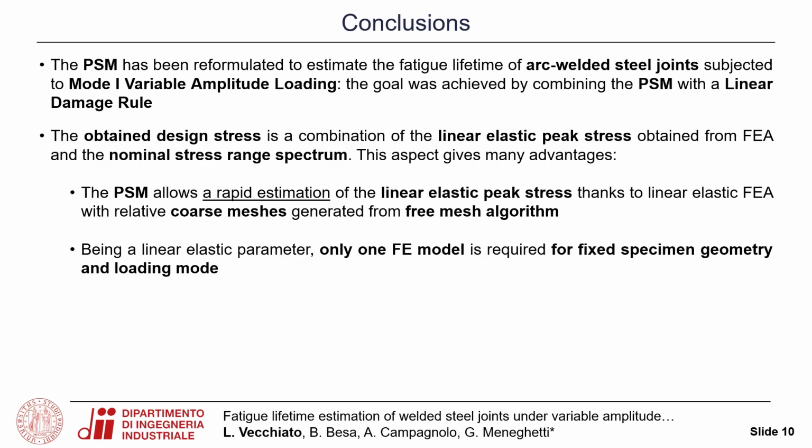The first advantage of adopting this procedure is the fact that the PSM can rapidly estimate the linear elastic peak stress, adopting linear elastic finite element analyses which have rather coarse meshes that are generated from the free mesh generation algorithm available in all commercial finite element software. Moreover, being a linear elastic parameter, only one finite element analysis is required for a fixed specimen geometry and loading mode.